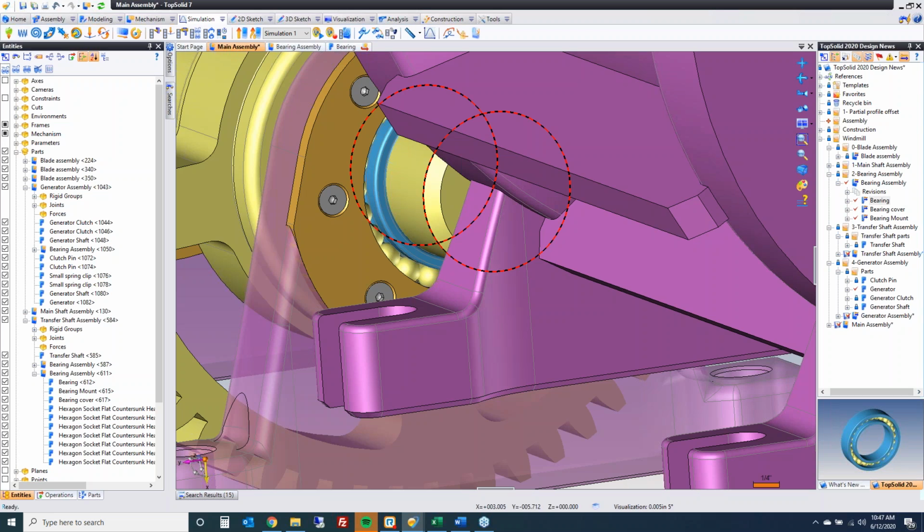Okay, last one on the design side that I'm going to show. Oops, I see a question from John. Tangent surfaces, what about the corners? There's a solution for that. You can do a swept surface or a lofted surface between those. Okay, the tangent surface has to have something to come off of at that fine point. There is no element for it to come off of, so you'd have to loft or sweep around that corner.